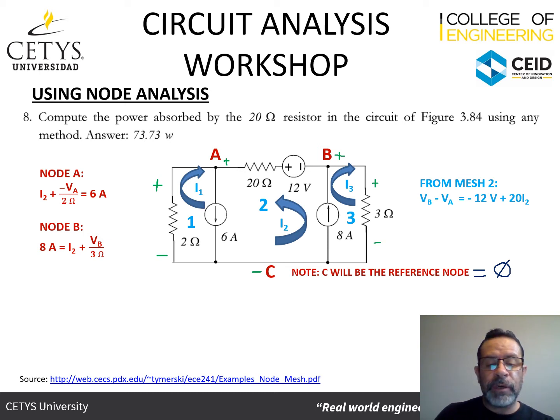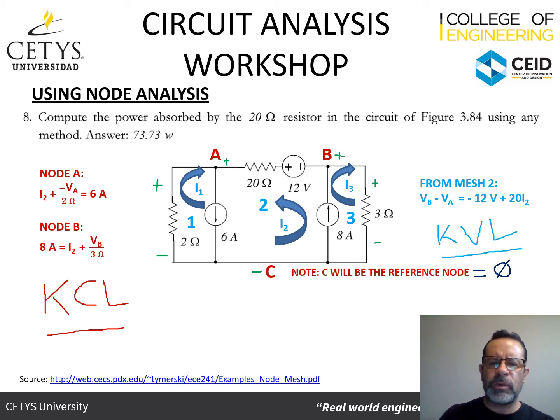Okay? And so the only thing we're doing here is that we're applying Kirchhoff's current law with regards to the nodes. And over here, we're applying Kirchhoff's voltage law in one of the meshes. We could have done it in all of the meshes, but we really don't need to do it in all of them. We just need expressions that relate all of the voltages we have. Now, once we have these, let's play around with these and see how we can find the values of the variables that we have there.